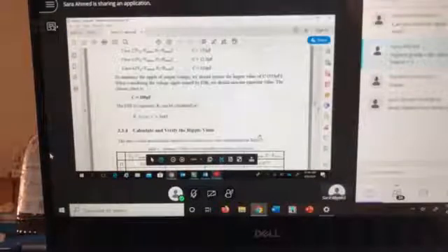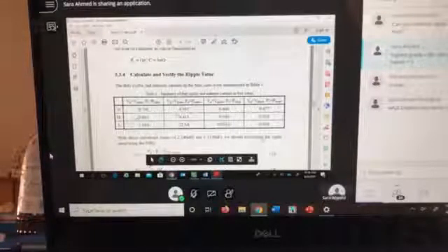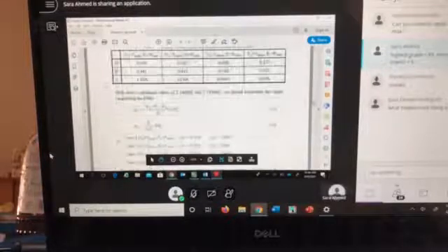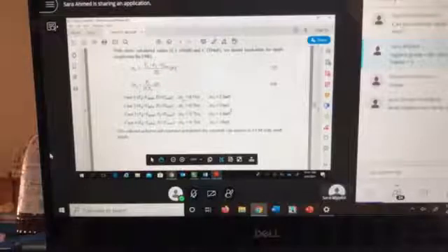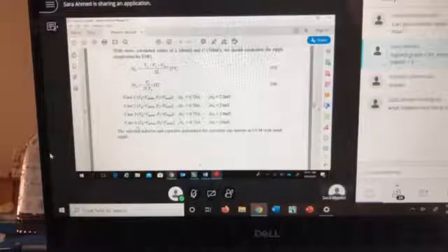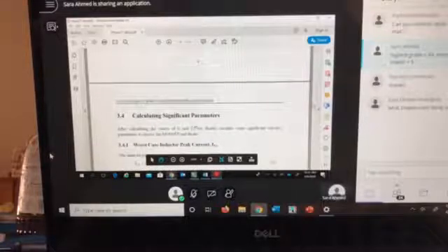So let's go back in here. I'm just showing the duty cycles for the different cases. That's a table to summarize what you have found from each one. And then this is just a verification that for each case, when you calculate it, it will give you the delta I of L and delta VO within the range that you need. You don't need this step, and it was not penalized for anything. It's just an extra step to verify that my choices of L's and C's meet all 4 cases on the ripple side. Okay, with that done, we go back to our problem here.